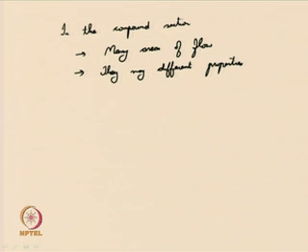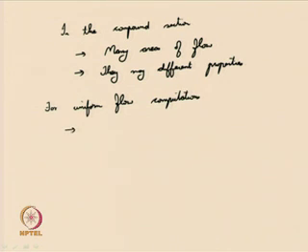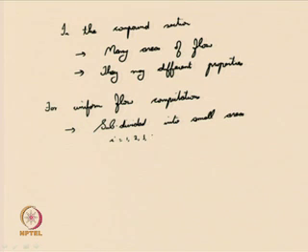So, for uniform flow computations, the entire compound cross section of the channel is now subdivided. The entire area is subdivided into small areas, say maybe n areas, i equal to 1, 2, 3, 4 etcetera up to n areas.